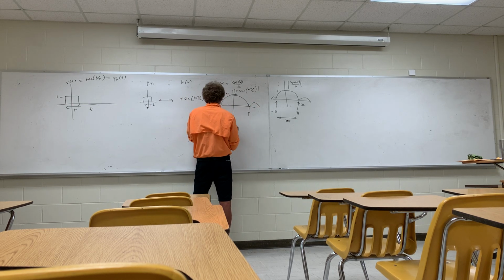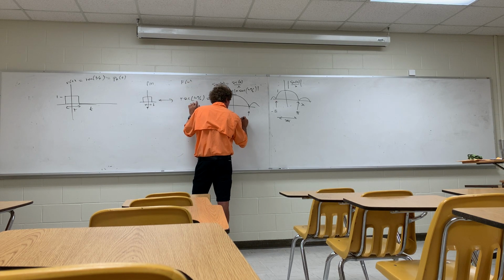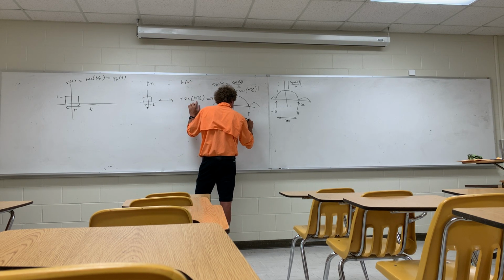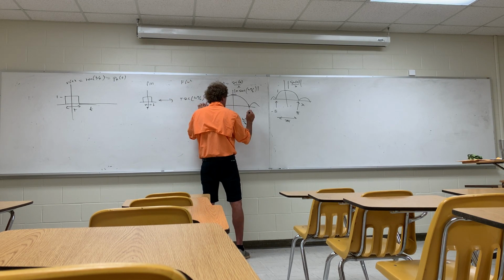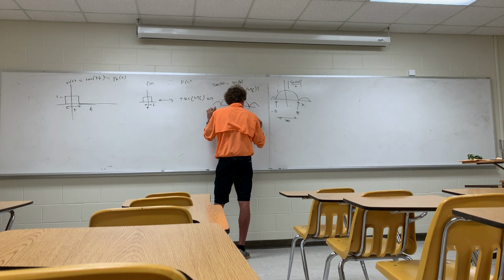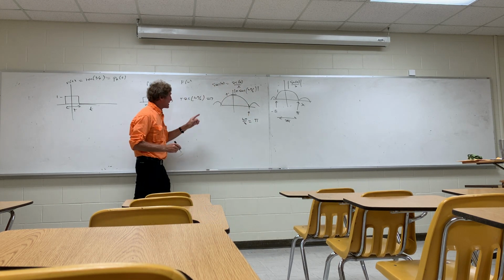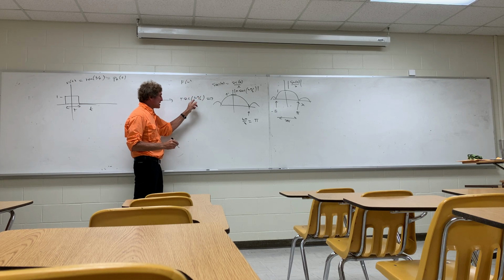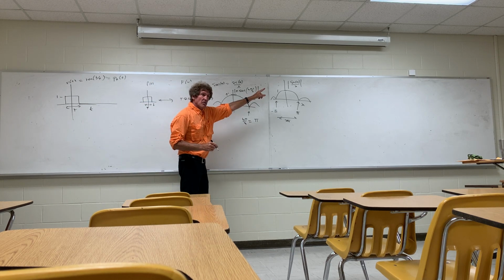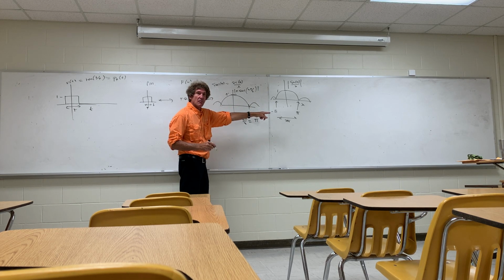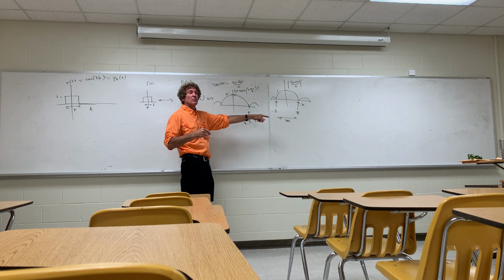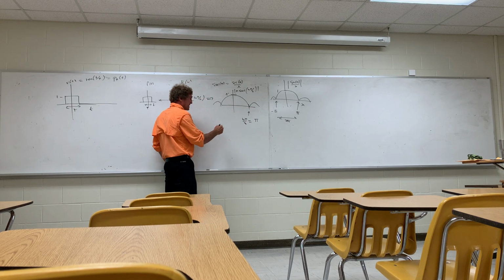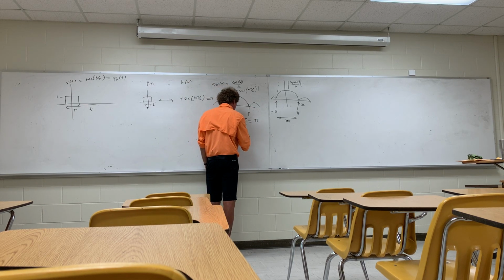Well, this point here is going to be found when omega tau over 2 is equal to simply pi. Y'all follow me? We're taking the inner argument here, and I'm setting it equal to pi because I know from what I sketched out, the first 0 of the sinc function is at pi. I want to find this so I can get the bandwidth. That's my goal on this. So I'd say that's the case. That means what? Omega is going to be equal to 2 pi over tau.